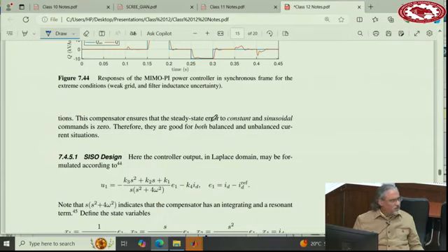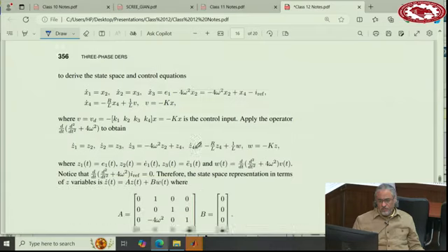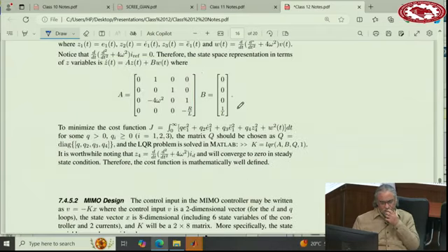And this is now PIR. I don't want to spend time with it because I'm not really convinced that this is the way to go. I don't want to advocate this approach. Because if you want to use R, why not do it in the stationary frame? In a stationary frame, you only use R, resonant, at the fundamental frequency, and then you get everything. Here, you need to use an integrator and an R at the double frequency, which is even more demanding than the single fundamental frequency, and then you will remove the problem. For the sake of education, it's good.